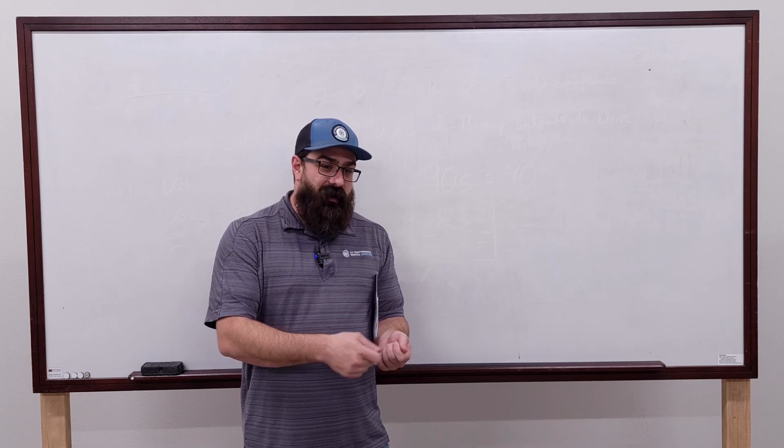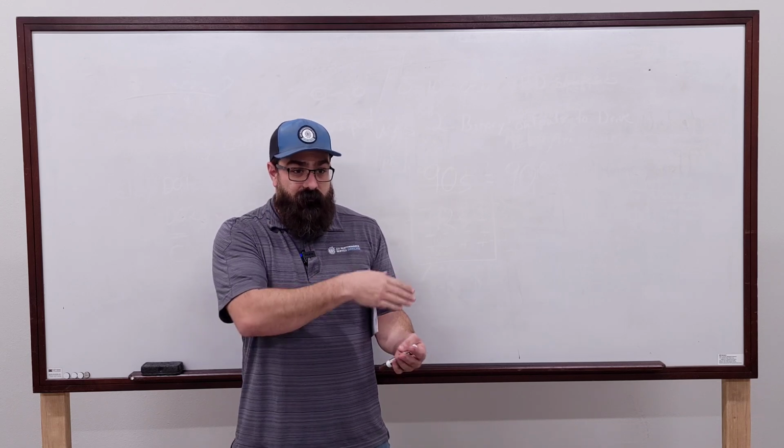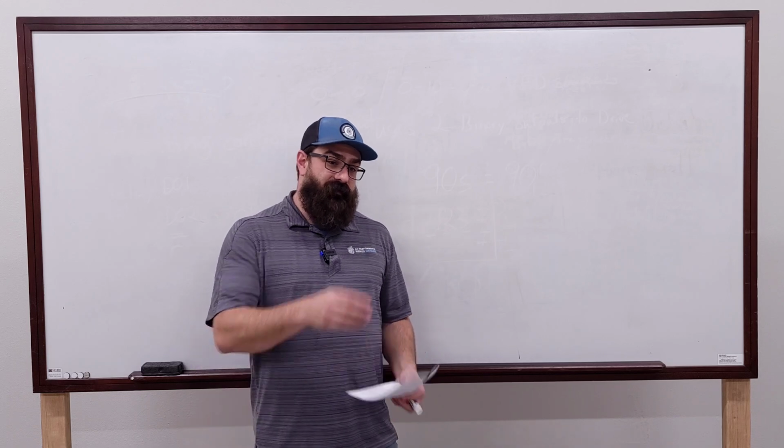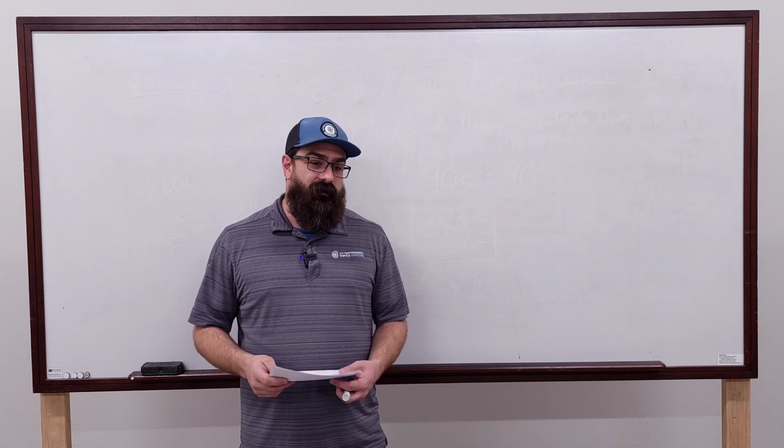If you've got 10 volts at the wire and the actuator's still not working, then it's probably a bad actuator, right? Because you know you've got voltage all the way up to the actuator. So the output's working because you've got voltage at the output and you've got voltage at the field device. Just now the field device isn't working.